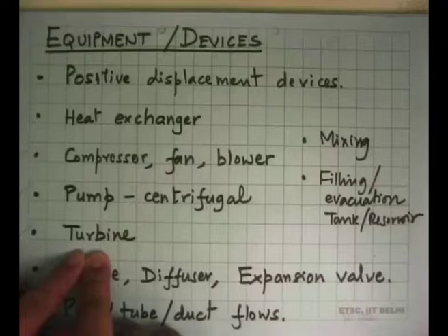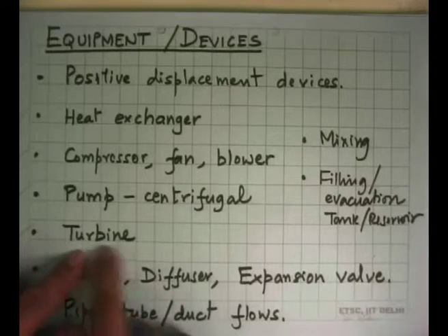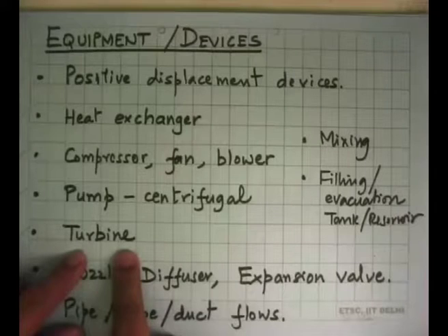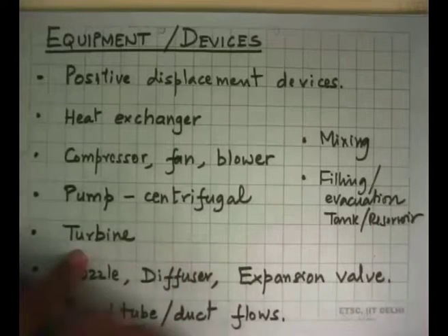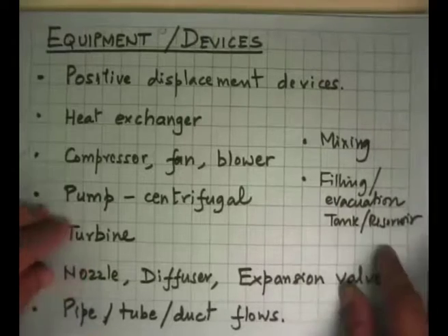We looked at gas turbine, steam turbine, hydro turbines, and we said these are work producing devices, and the most efficient way that we can get them, thermodynamics tells us, is an isentropic process in these turbines. And we said that if these were real machines, then there is some irreversibility in the flow, so operating between the same pressures, what does the process look like?